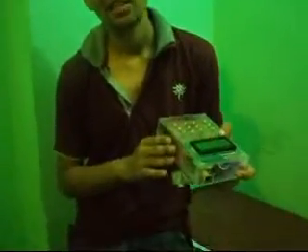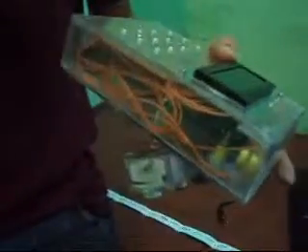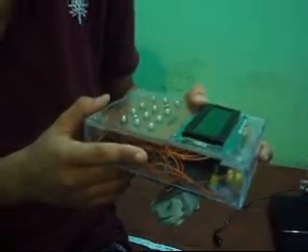But in real life situations, that reflecting surface is not always available. For example, to measure the distance between the 2 points on the ground, the reflecting surface is not there. So this device uses the principle of tilt sensing using the accelerometer, and based upon the tilt sensing information, the device calculates the distance. So this device has the advantage over the conventional handheld electronic distance measuring devices that use ultrasonic distance sensors.